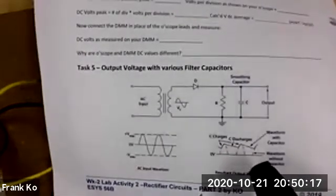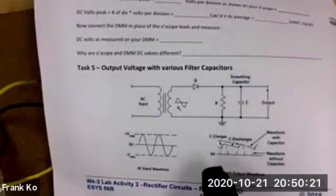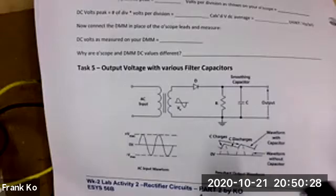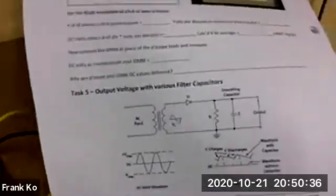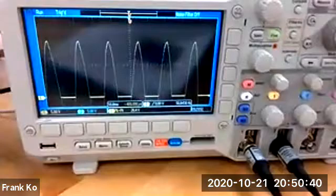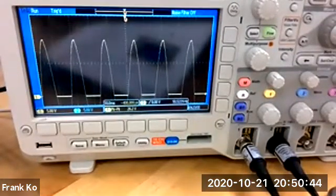The desired observation is for us to see the effect of different size capacitors on how they change the amount of ripple that is going to exist on our waveforms. So I would recommend doing this. I would recommend setting your oscope displays right now to the way that I've set this up. This will make it easier for you to see the changes of ripple.